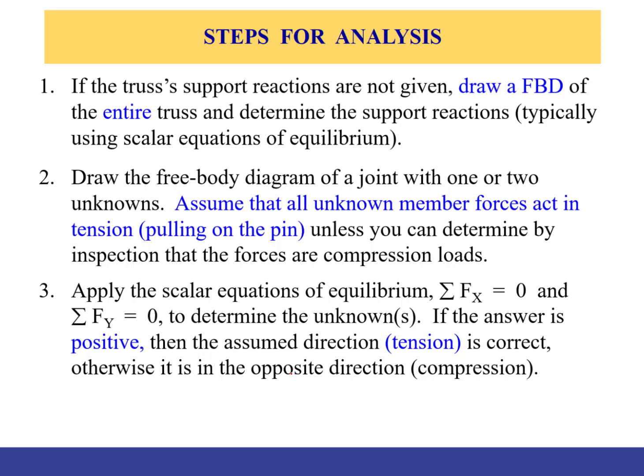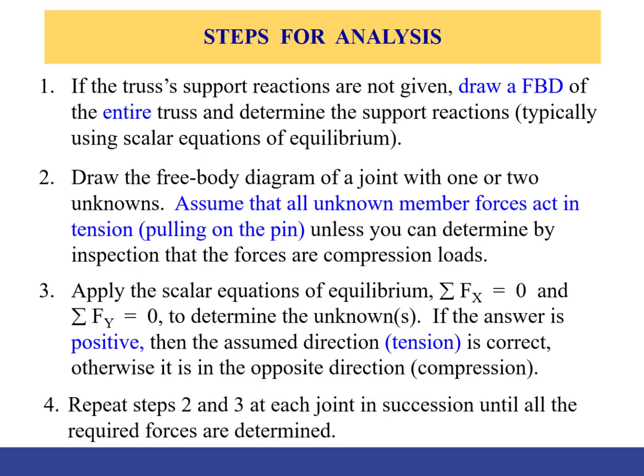If your result comes out positive, it means your assumption is correct, and that member is under tension. If the force comes out negative, then it's opposite to your assumption, so therefore it should be compression. Sometimes you have to apply the equations of equilibrium to all joints to find all the unknowns, or if you're lucky, you can find a joint where you have only one unknown to find the result.